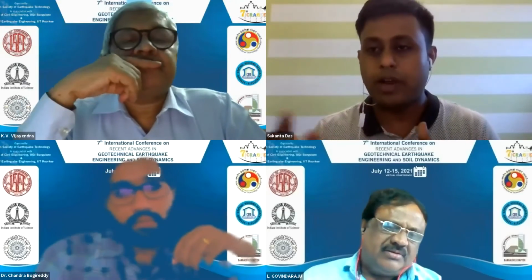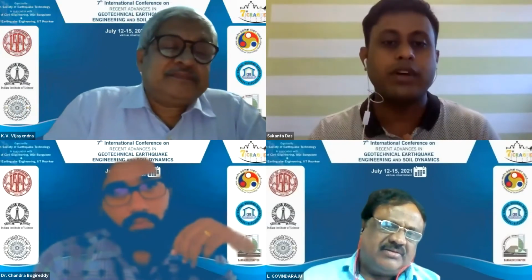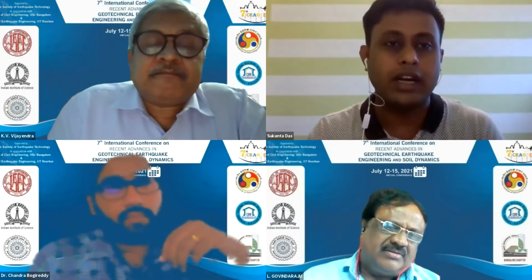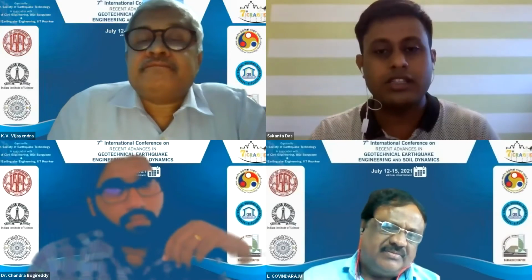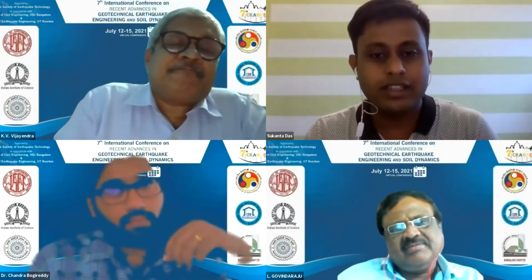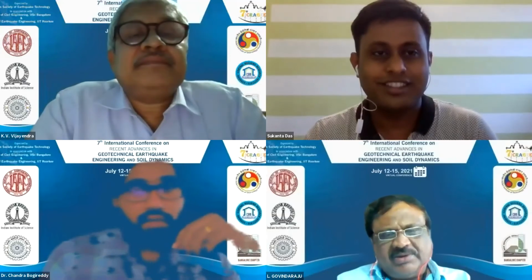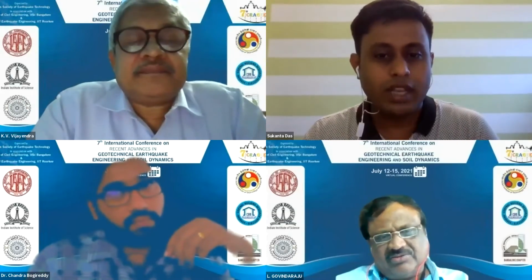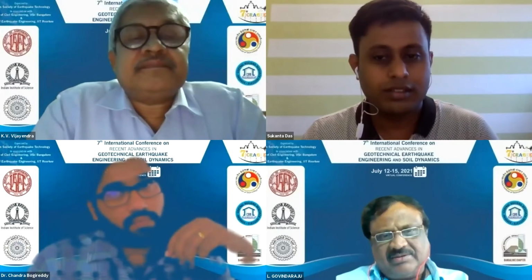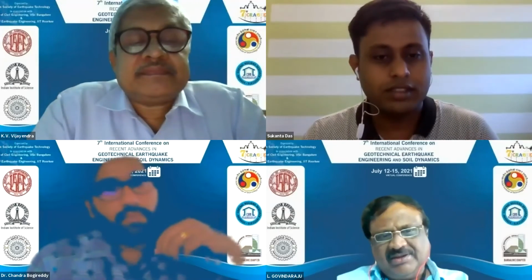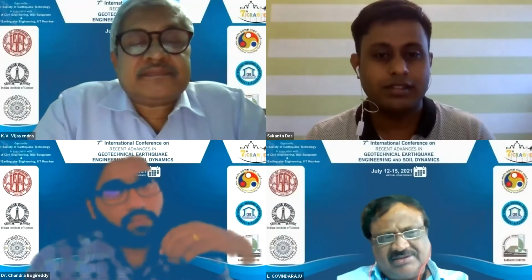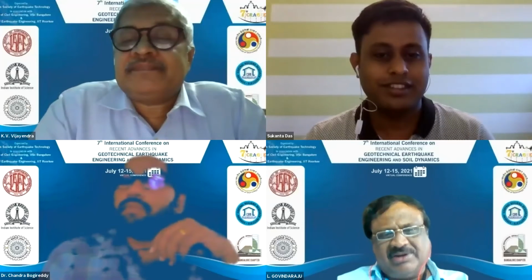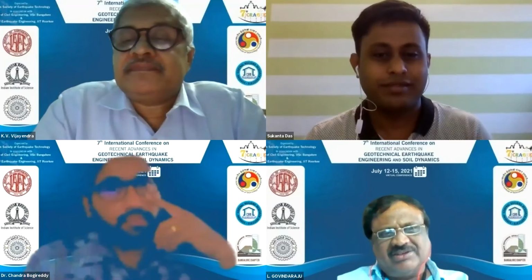But again, from our extensive studies, we have found it should not be 27 degrees or 30 degrees. It should depend on the sloping angle beta. But as per BIS, it is recommended to be 27 degrees. It also depends upon the type of footing, whether raft, rectangular, square or circular, because the pressure bulb varies. In the literature people have recommended 27 degrees, and we have done some experiments at our university and are also getting 27 degrees.